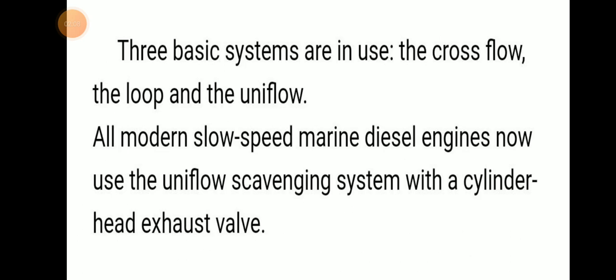There are three basic systems: cross flow, loop and uniflow. All modern slow-speed marine diesel engines now use uniflow scavenging with a cylinder head exhaust valve. It is now common: uniflow scavenging with a cylinder head exhaust valve.